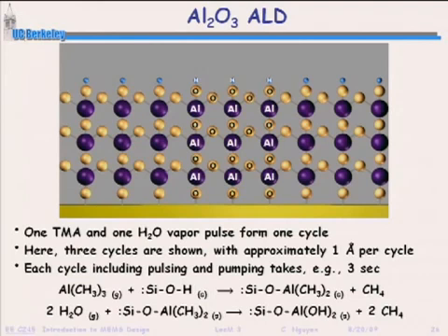So if you wanted to deposit something else on top of this, would you? No, if you were going to do ALD again, you'd want those OH groups there. Right, but if you're done with ALD and you're depositing another layer of something else? Usually if you go into an LPCVD furnace, you're going to be at very high temperature, so you're going to get rid of those OH groups anyway, and deposit your film over that. Okay, so this is what you could do with ALD.